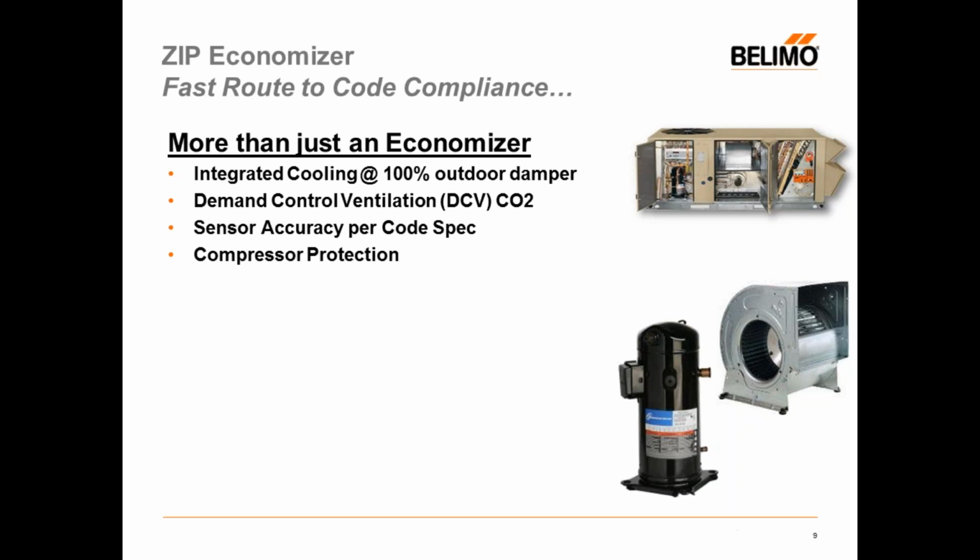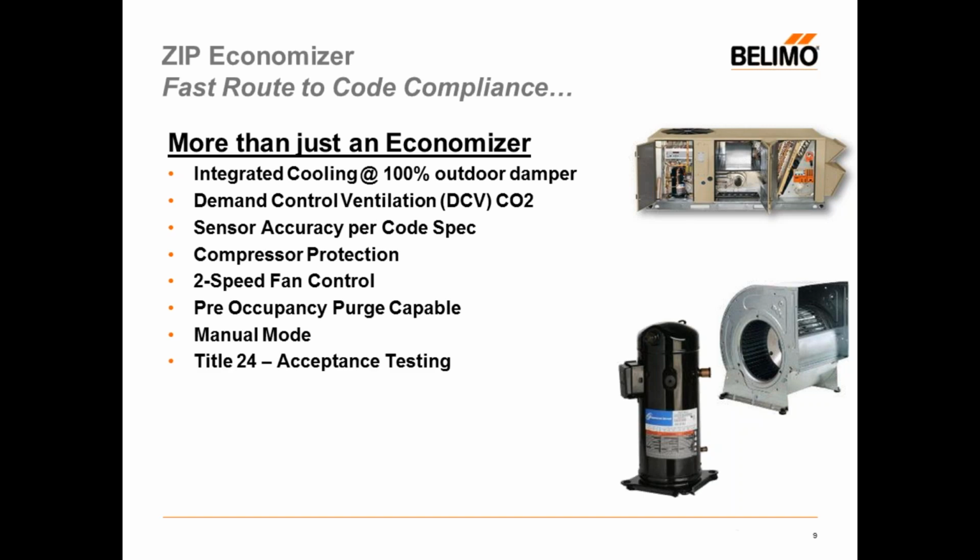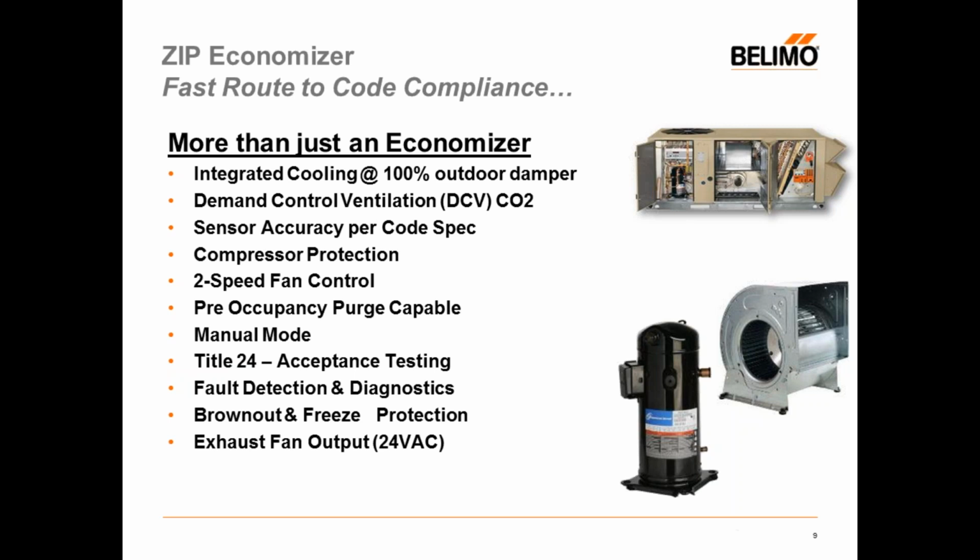The ZIP includes some additional compressor protection strategies designed to provide additional energy savings: two-stage span control, the ability to purge the building before occupancy, a manual mode for operational checkout, fault detection and diagnostics, brownout and freeze protection strategies, and an exhaust fan output for pressure relief.